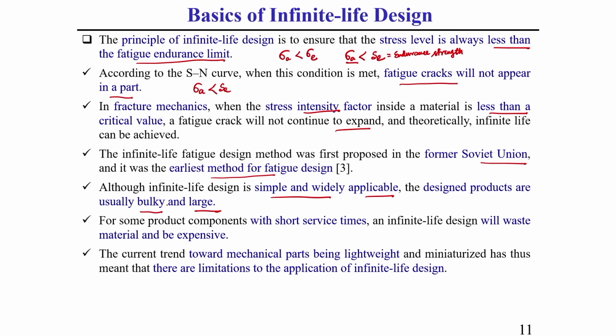So, here generally the factor of safety and other things need to be considered very high. Then what happens due to this high factor of safety? The dimensions, that means the thickness of the material and other things, are generally considered a little bit on the higher side. That is why it is generally bulky and large. That is why for some product components with short service time, infinite life design will waste material as well as require more cost, that means it will be more expensive.